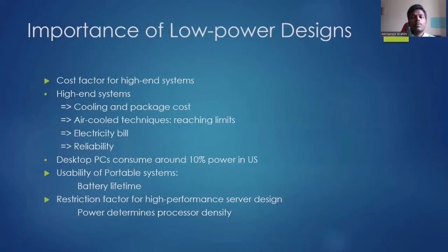Importance of low power designs. First, it is a cost factor for high end systems. High end systems need cooling and packaging, so the cost is high, air cooled techniques are reaching their limits, the electricity bill will increase, and the reliability of the system will change. Desktop PCs consume around 10 percent of power in the US, since most people are using PCs.